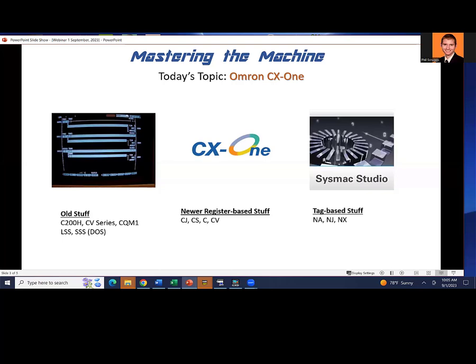And then when I go out and teach these classes, I talk to the students and they say, you know, there's a newer platform out, the Sysmac Studio platform. And it's pretty much all tag based. So you may be familiar with that. If you've been on any of these webinars, we talk about Allen Bradley, for instance, has the 500 platform. The 500 is register based. You have B3 registers and N7 registers. Some of you may be very familiar with that. And then there's the newer ControlLogix, and ControlLogix is all tag based, where you just type in a name for a tag and what kind of tag you want to use, you know, an integer, double integer, a real number, or a Boolean. And it just automatically creates that tag in whatever type you want.